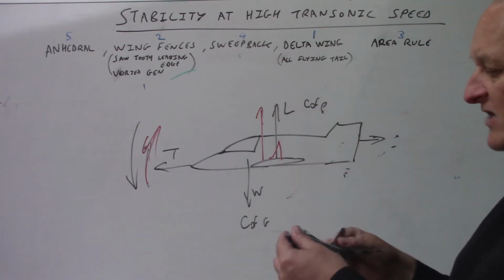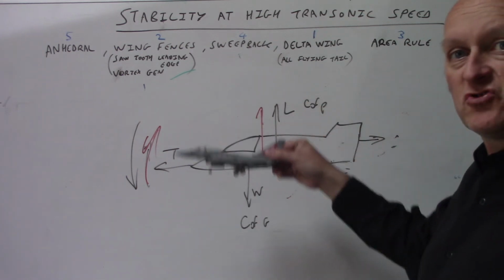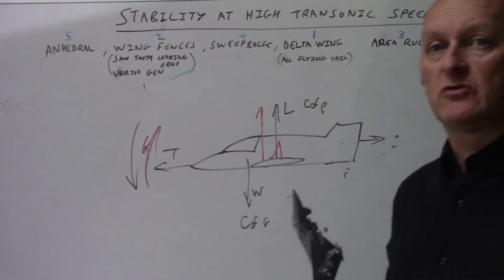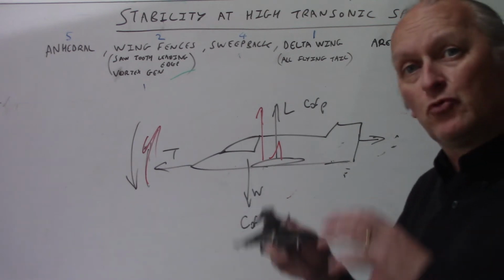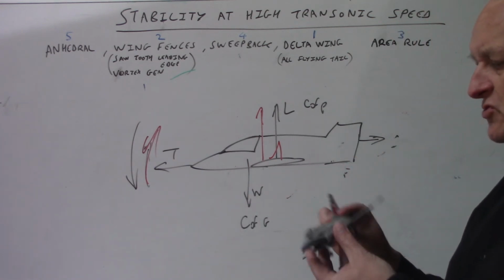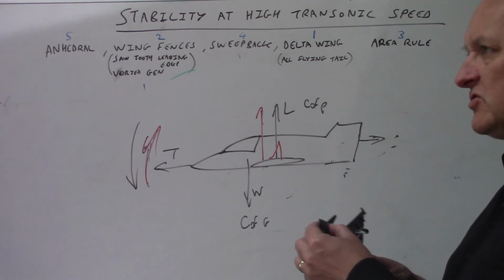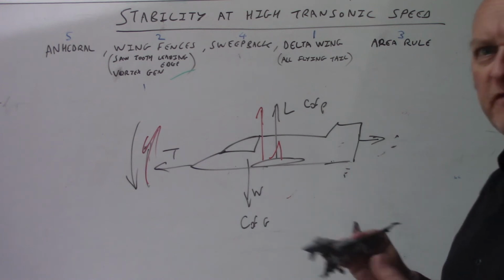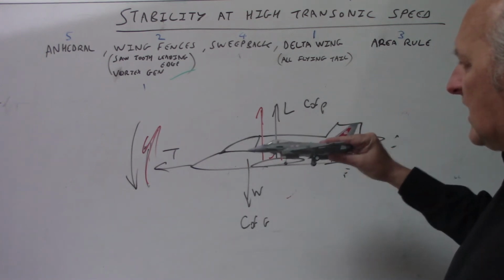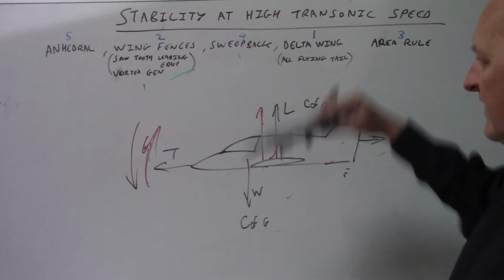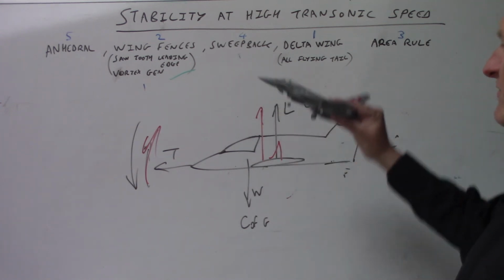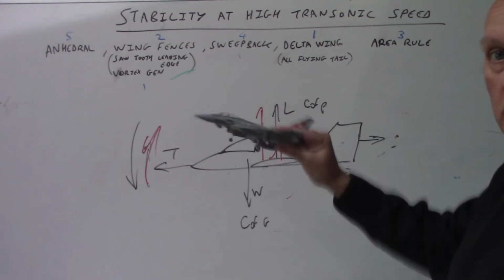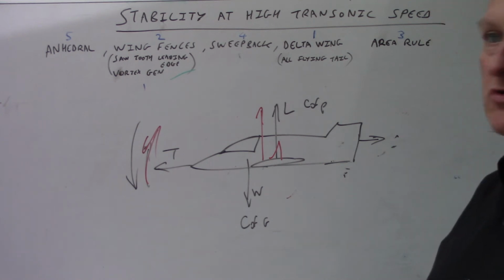Now, if that was nice and gentle, you've got a bit of a shockwave here, which can happen on some aircraft depending on the way it's designed. But the very first supersonic aircraft were not designed for this, they hadn't worked all this out yet. They knew something was going to happen, but with things like the de Havilland Swallow, with Geoffrey de Havilland on board, which was an early delta aircraft, like a mini Vulcan, basically at critical Mach it suffered a violent oscillation. This shockwave appearing and disappearing onto the trim of the aircraft, so you had that going on. Two pilots flew, one died, one survived.